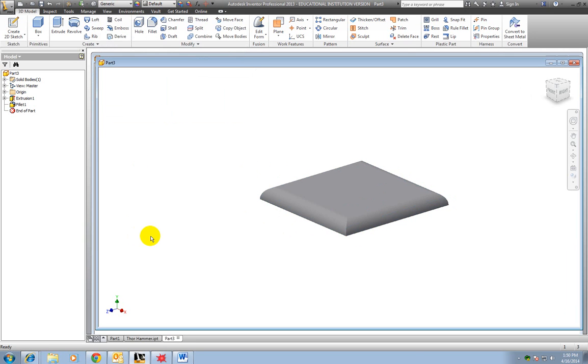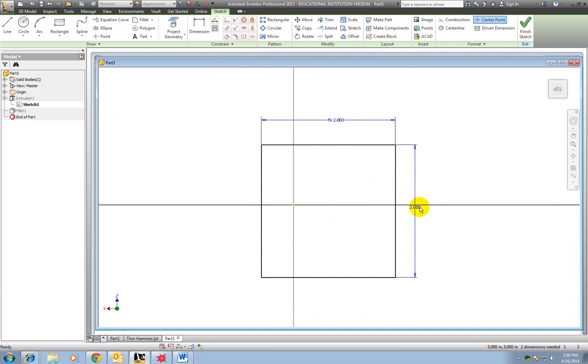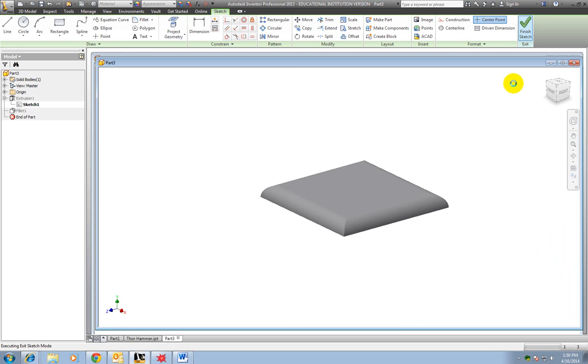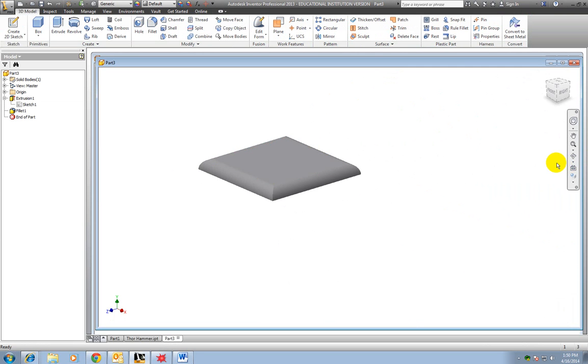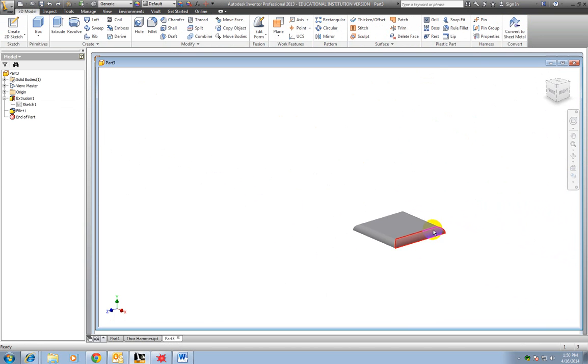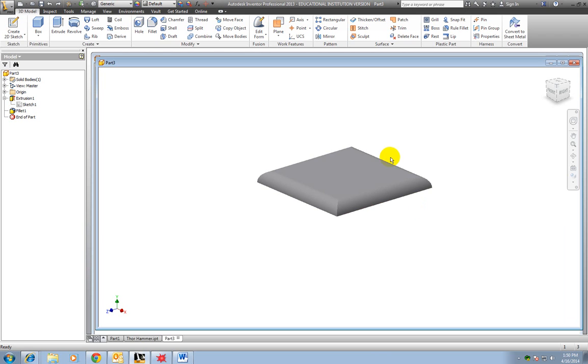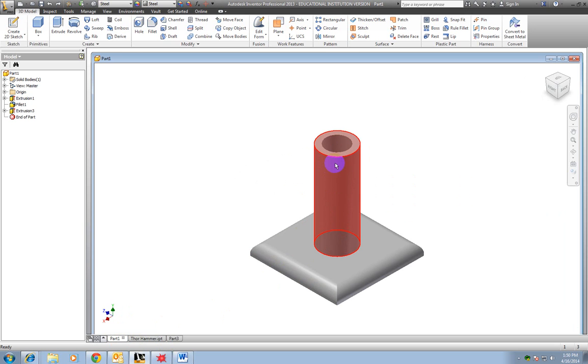And click OK. All right, just to show you, you don't have to follow along with this part, but if I edit this sketch and change this first number to say 24, like we had said, and click Finish Sketch, notice it still looks the same no matter what. All right, so I'm going to undo that, so that way I can go back to the way it was. All right, so now I want to draw the little part that comes up to put the flag in.